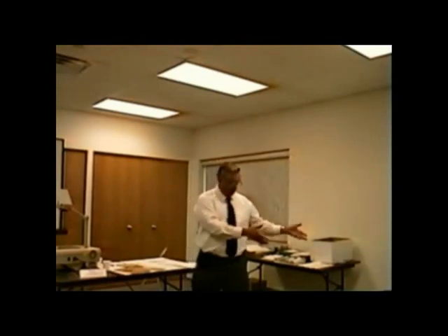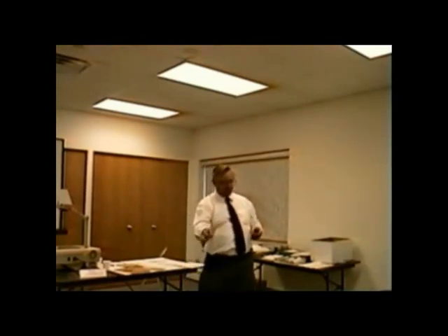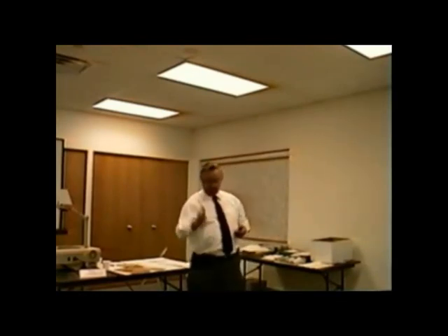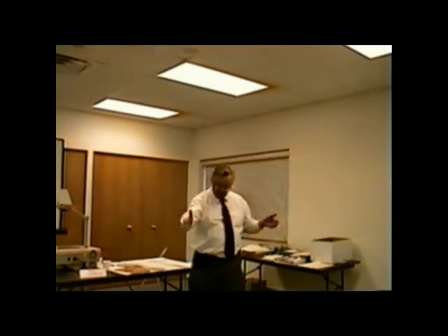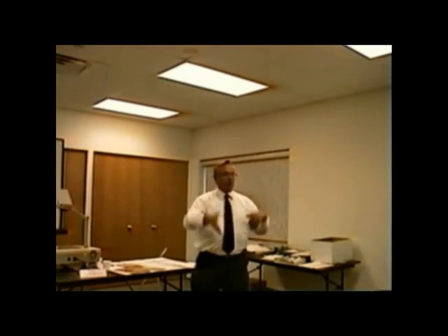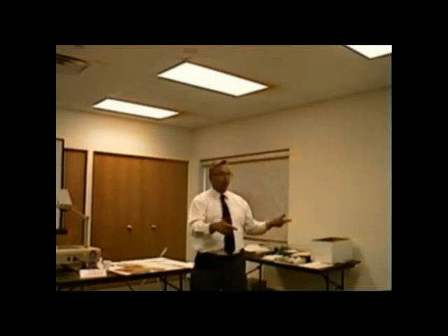Mr. and Mrs. Jones, did anybody ever show you how we safety check your furnace? You let them watch the fire, you say, see, I'm pulling the blower wire. Or I'm putting a piece of cardboard here. So if your blower motor fails, we know that the fire is going to go off. And you let them sit there and watch it with you. Boom, the fire goes off. You say, see, it goes off.